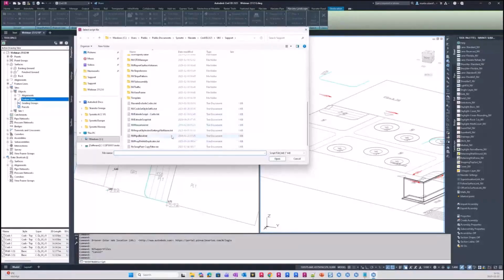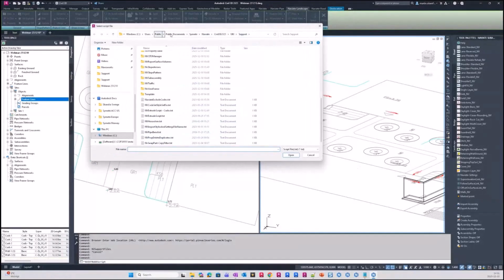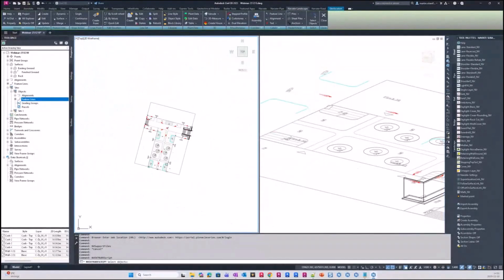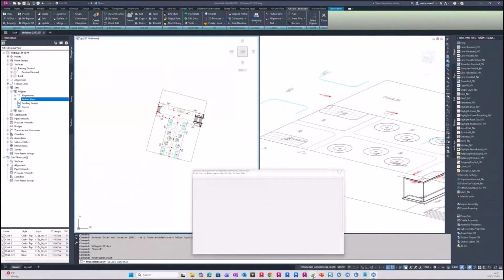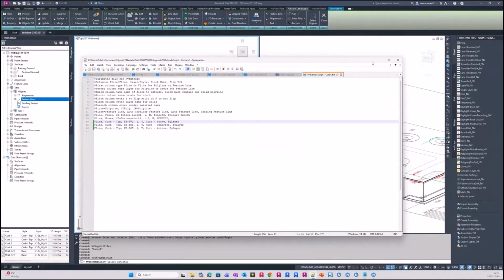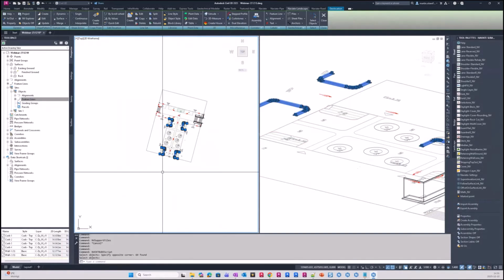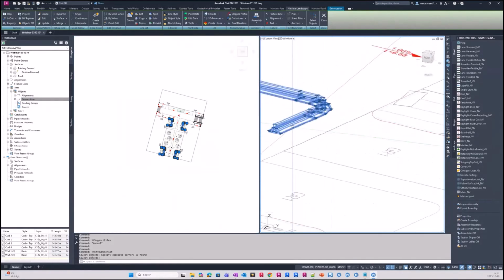And it will open the support folder, and you can just pick this script file, like in this case, extrude script curbs. Then you just click open, and now I can drag. You can drag over everything, because if it's not finding these parameters, it won't create anything. So I can just pick everything, hit enter, and it will create my 3D solids here.